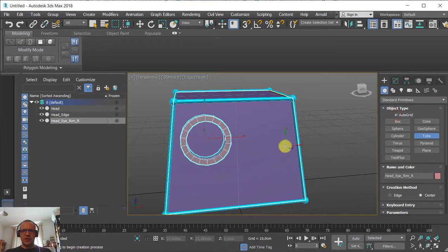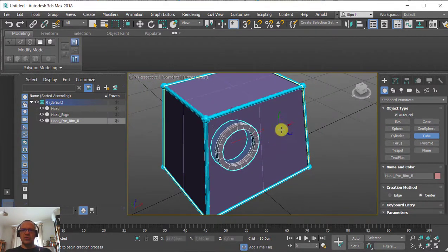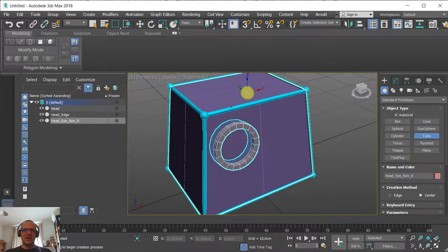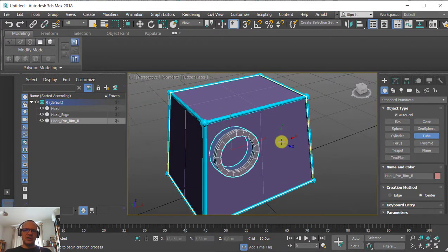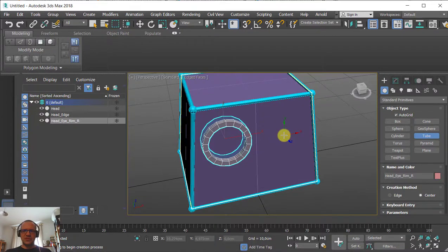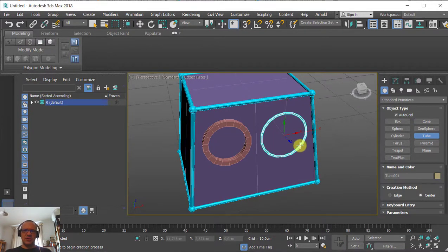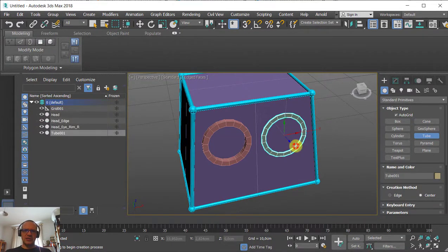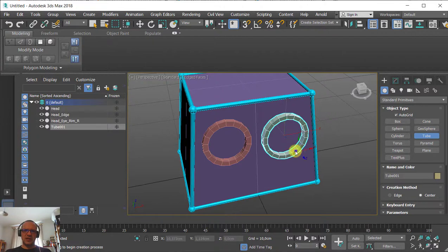Autogrid will turn our cursor into an interactive surface checker. If I'm on this surface, it will recognize the surface orientation and angles. If I'm on top, it will adjust the location to there. If I'm going to the side, to there. So we'll start from the center, drag it out, outer edge, inside edge, height, and click and done.